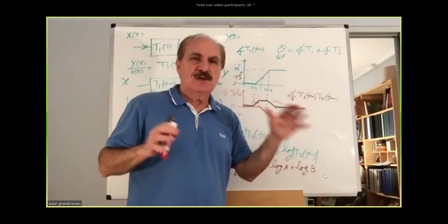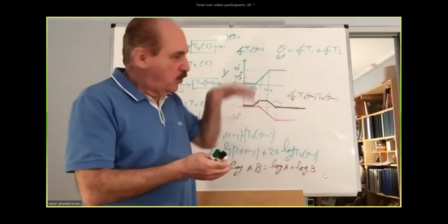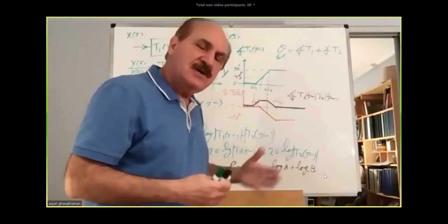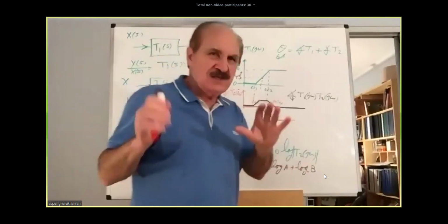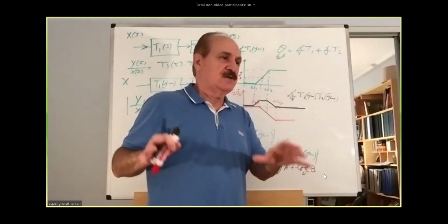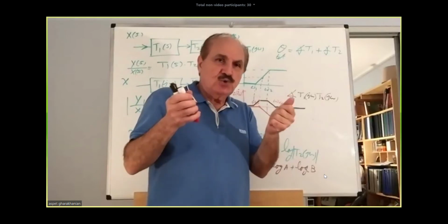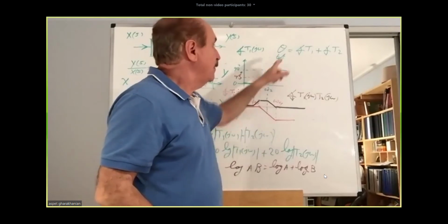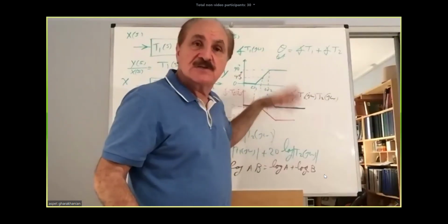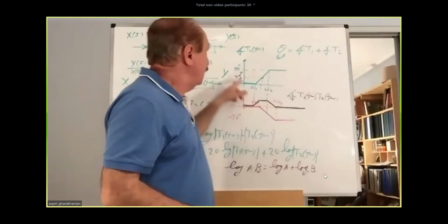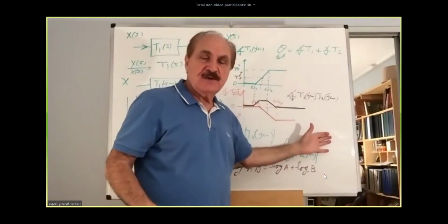Compensations, and so on. Often we want to know where to put that maximum in order to shape frequency response and to get a system stable. That is an art by itself. Only control engineers can do that properly, and their tool is Bode plots. Bode plots: gain against frequency, in fact 20 log of gain against the frequency, and phase angle against the frequency.